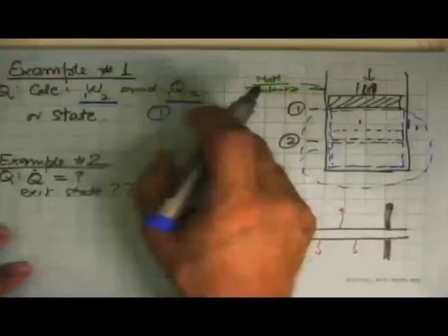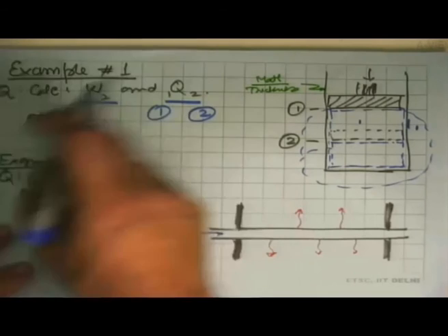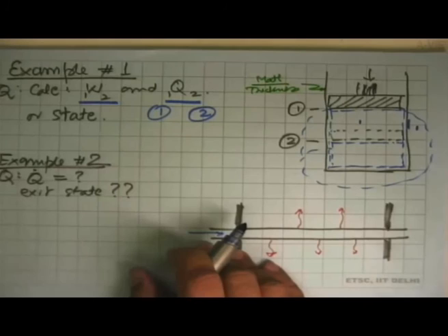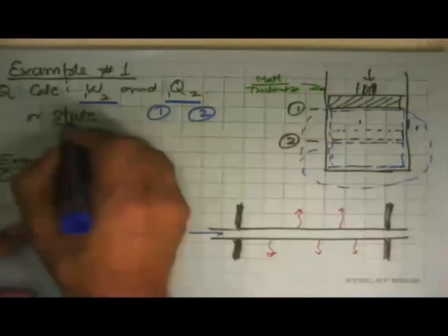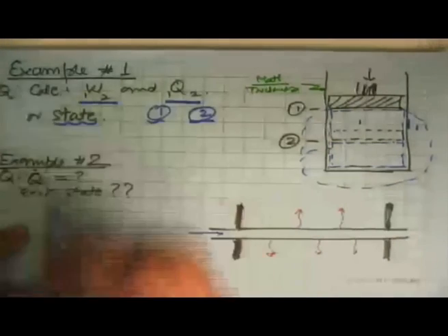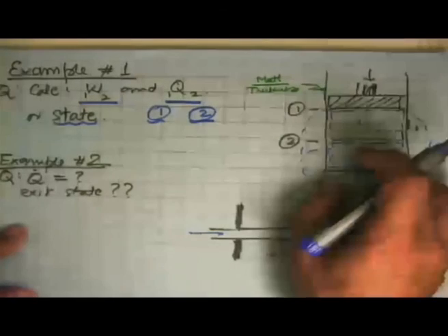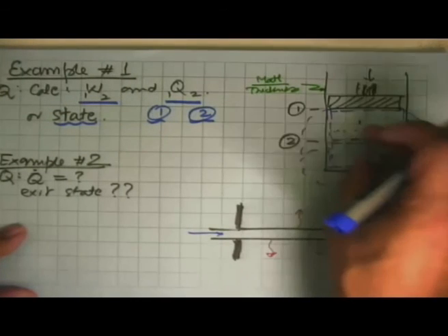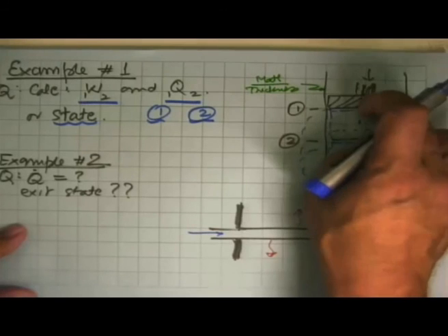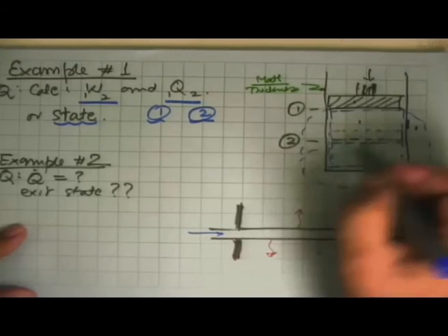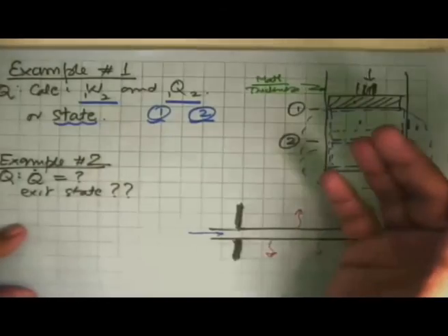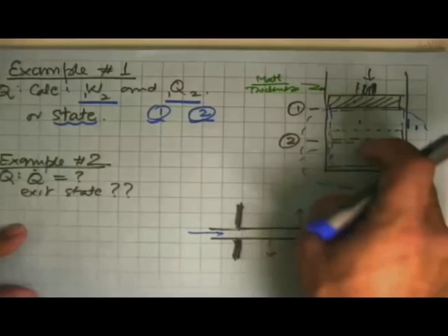So if, of these three, any two are known, the third can be calculated. And that's what the entire exercise of problem solving in thermodynamics becomes. So that's what we need to know: that to get the states, we need the properties. And this information is important because from this, we start doing the engineering of this device. For example, if in this process we know that this is the maximum pressure that the substance will take, we know what we can then design: what material should we have here, what material should be there for the cylinder, how thick it should be, how it should be made. All those decisions get taken based on these thermodynamic considerations.